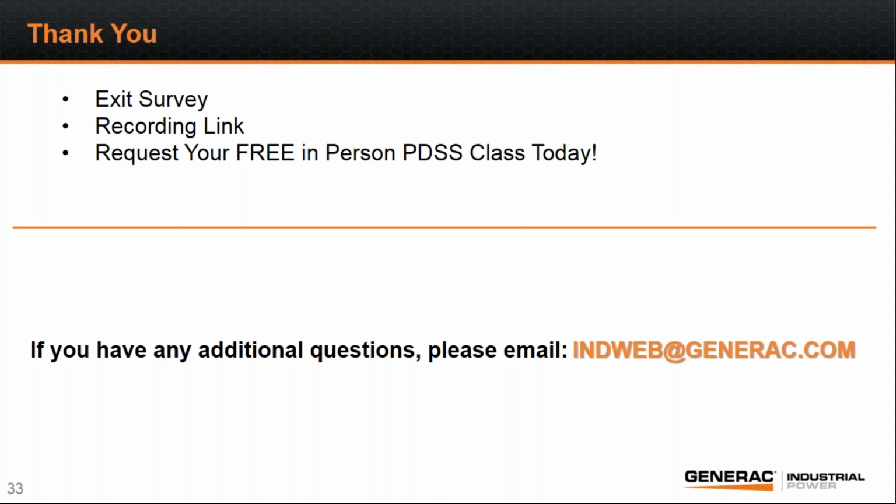When you discussed Y delta starters, that was for closed transition Y delta starters, correct? Within our sizing program, we have both open and closed. The closed will give a little bit lower result than the open transition. The open transition spike will be a little larger. So we try to model both. And we're assuming that motor is going to be allowed to work for 5, 6, 7 seconds to get as close to rated speed as it can before it transitions over.